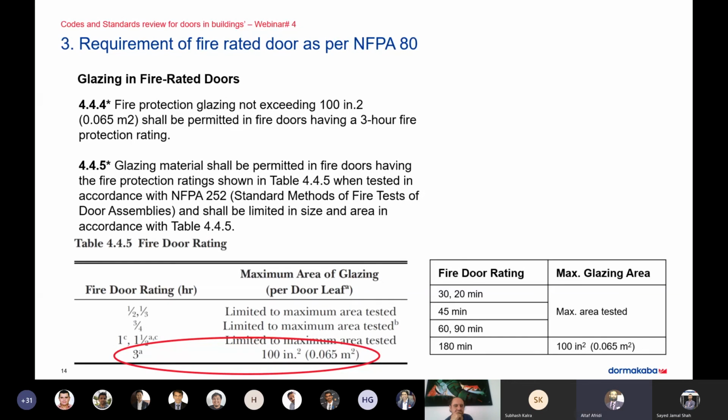In such cases, mostly they use a floor closer, which is a fire-rated floor closer, and the door is tested for this purpose. There are always arguments on this door because there are no stops and the gaps on the sides are bigger as compared to a single acting door, because in double acting we need more gap for the door to operate.